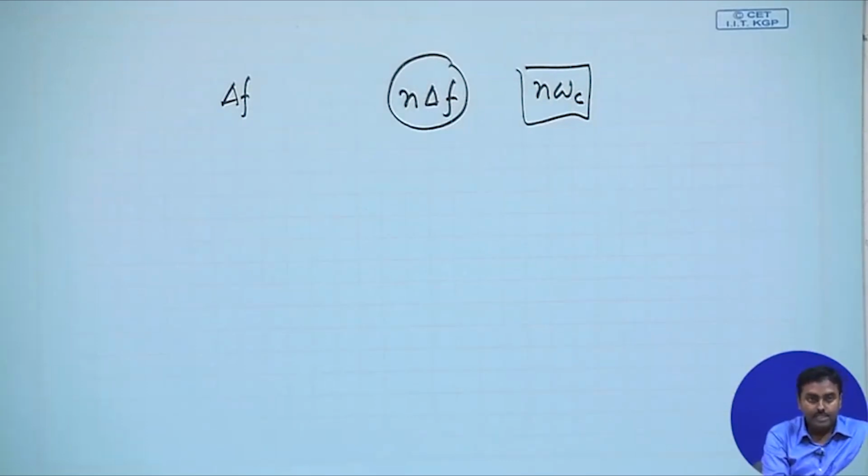Now we will try to see, if we target a particular frequency where we wish to put the FM, and we target a deviation independent of that frequency, how do we really make a circuit out of that? That is where we will be doing this FM in multiple stages, or this nonlinearity that we are putting will actually do it in multiple stages. So, let us try to appreciate that part.